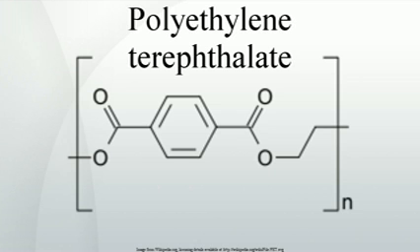In order to protect the spinnerets, an efficient filtration of the melt is, in any case, necessary. For the time being, the amount of POY made of 100% recycling polyester is rather low because this process requires high purity of spinning melt. Most of the time, a blend of virgin and recycled pellets is used.